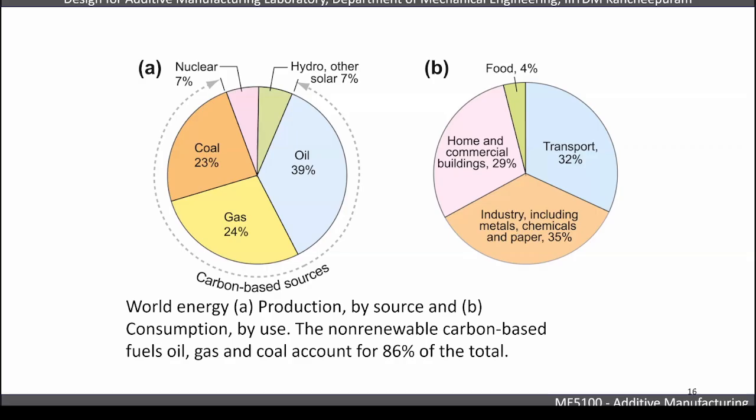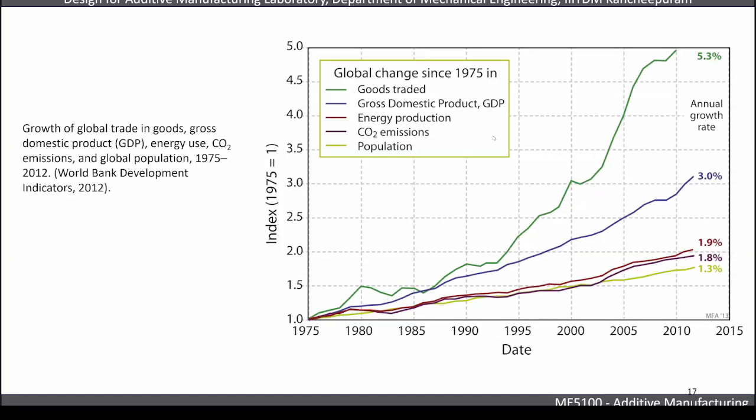So we take energy consumption in kilowatt hours, convert that into CO2 emissions, and then allocate them to various impacts like global warming potential, ionization potential, and water eutrophication potential. The SOx, NOx, and CO2 emissions are used to compute the final impact, right? So that's the reason. With 35% energy consumption, if the energy mix is very poor and heavily dominated by fossil fuels, we'll have more emissions. So we need to cut down on process emissions, especially around manufacturing processes, which are highly energy intensive, right? So that's the need.